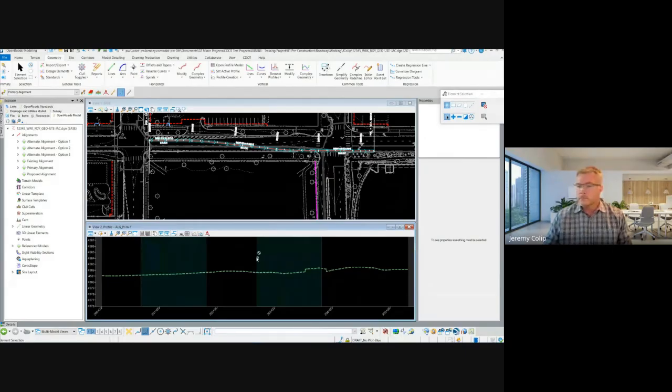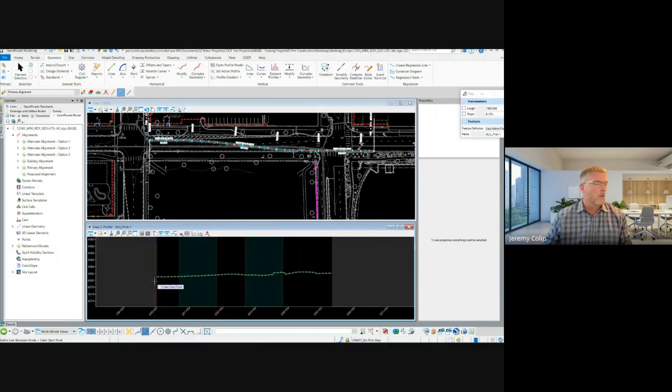On the method that we use, one of the things that I use quite a bit is actually a profile from point to point. And again, best practice is drawing in construction lines, those types of things. I'm skipping that right now just to make sure we have time to get through everything. But best practice would be to draw in construction lines that you want to have.